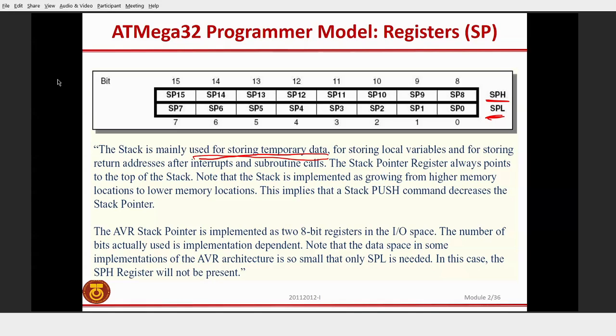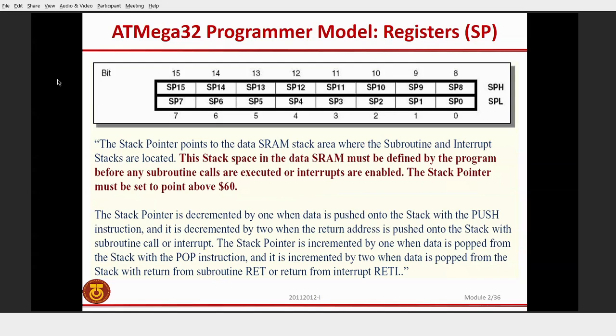So it needs to store the current context. Context means the current value that is executing, because after the function finishes executing, you need to return back. When you return, you need to get back the data that you temporarily stored. So this is where the stack pointer comes into the picture, to store temporary data for a temporary execution like that. We'll come to this in our final chapter on the stack pointer in assembly language.